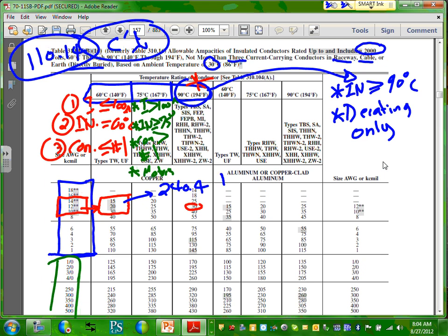If you go there, it will tell you exactly what I told you about these particular ones. This applies to 18 and 16. Guys, we use 18 and 16 only as fixture wires and in Class 2 and Class 3 control circuits. Everybody knows branch circuit list and number 14 is not used. Any question? The same thing on the aluminum side, except they give it only for 12 and 10. Number 14 aluminum cannot be used as a branch circuit. Not like we use a lot of number 14 aluminum. Any comments, guys? Any question about how to use this table?